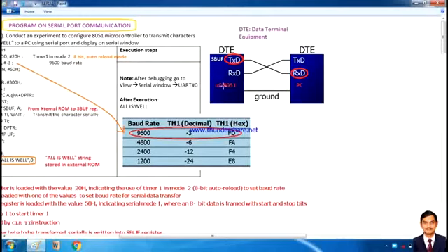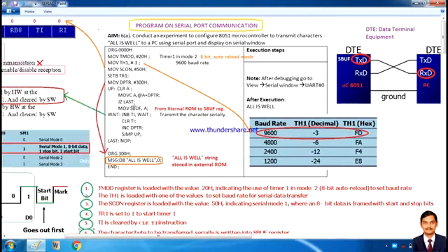As you can observe in this diagram, inside the 8051 microcontroller there is the SBUF register. Prior to sending to any other device, the data must be stored in the serial buffer first. Later it will be appended with the start and stop bits, then transmitted serially bit by bit. Now I am going to transmit to the other DTE over a single-line channel.